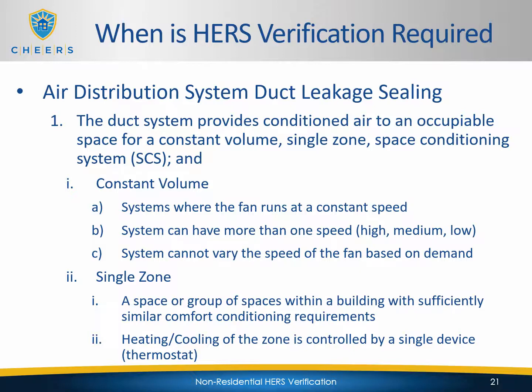So a heating or cooling of that zone will be controlled by a single device, most likely a thermostat, and those zones are all going to be single. So we oftentimes see this on the residential side where you'll have the upstairs and downstairs of a home be in different zones because of the way the stack effect works and heat rising upstairs, you have different comfort needs.